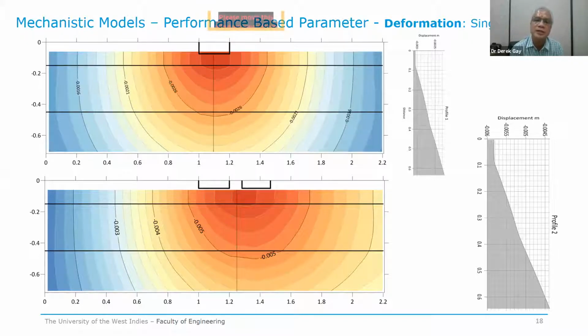Now what is interesting here as well is that in performance-based design, we deal more with deformations than we deal with stresses. And what is interesting, therefore, is that of the deformation experienced at the surface of a pavement, actually 90% of it comes from the deformation of the softer materials, which is the base, the sub-base and the subgrade. Because although the stresses are less, the modulus, remember from the top of this talk, was 10 times smaller. For example, the base stiffness is 10 times smaller than the asphalt.